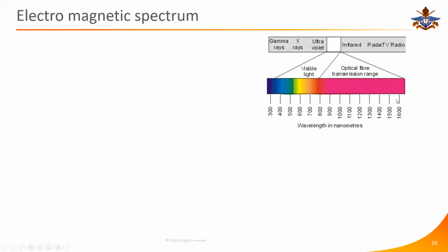The problem with this type of wavelength is you will not be able to see it with the naked eye. So, in effect, working with fiber optic cables is fairly dangerous. The reason being, if there's a fiber cable break, or if you look into a laser diode directly, you will not be able to see any light. But the light is there and it can cause severe damage to your eyes. It can cause severe damage to your skin.